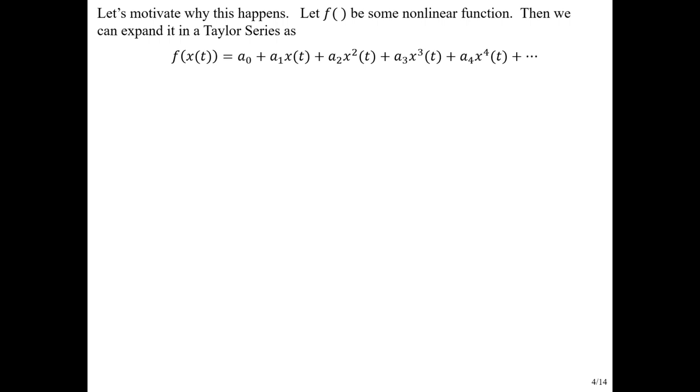So we've got some nonlinear function. We're only going to be considering systems for the moment that have no dynamical nature to them. So not like an RC circuit where the output depends on inputs from now and all past values as well. That would be a system that has memory. We say that an RC or an RL circuit has memory. But this is what's called a memoryless nonlinearity.